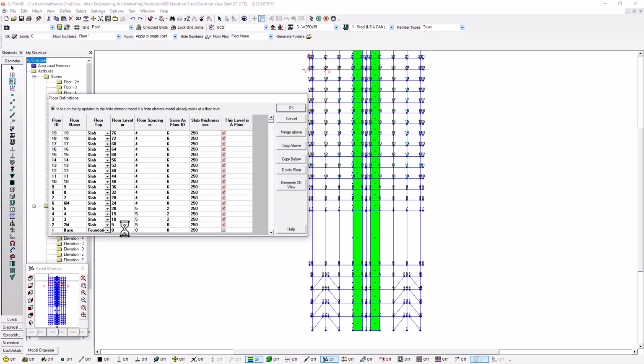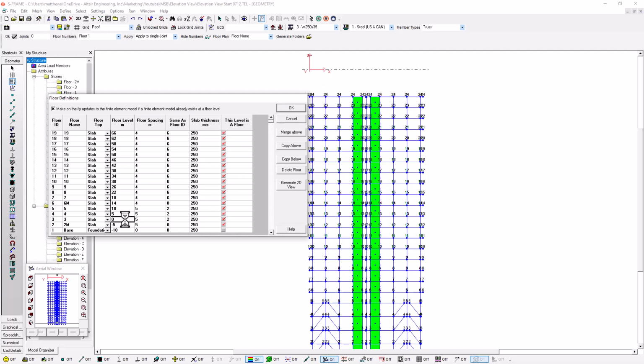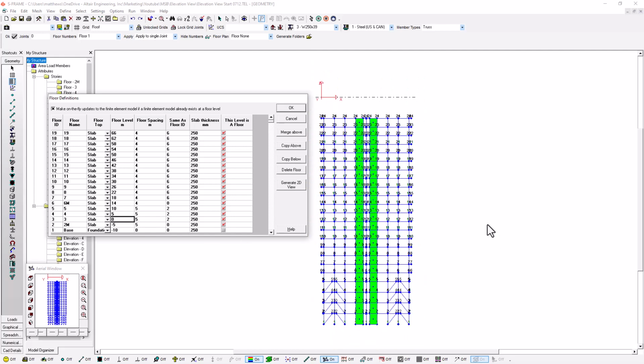One example of this could be that we want to change the base elevation. So rather than starting at 0 meters, maybe we start at 10 meters below 0. So negative 10 meters. And again, every floor level has dropped another 10 meters. When I click outside of this cell, I can see what that looks like. And once I go back out of here, my UCS is actually way above, but my floor spacing hasn't been changed, just the elevation of each has changed.